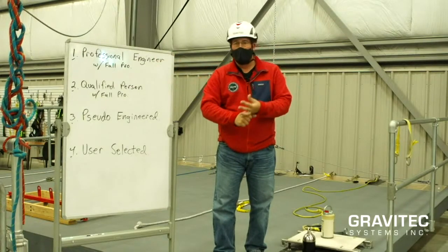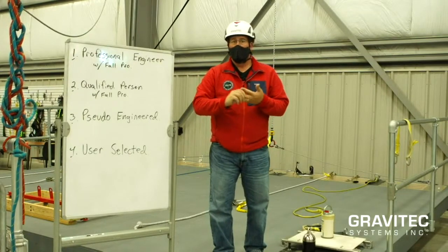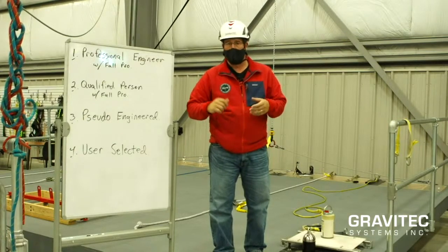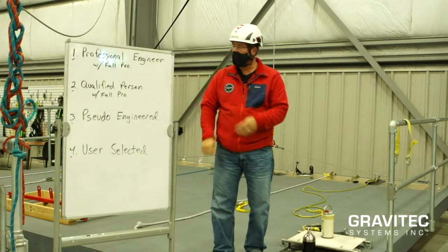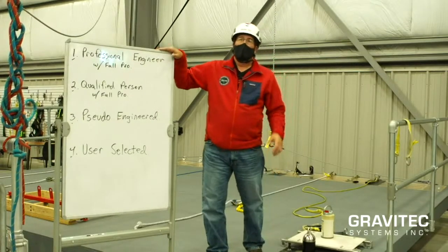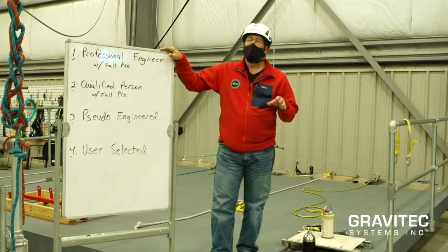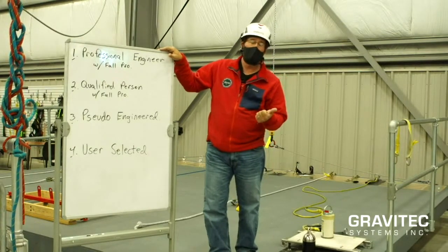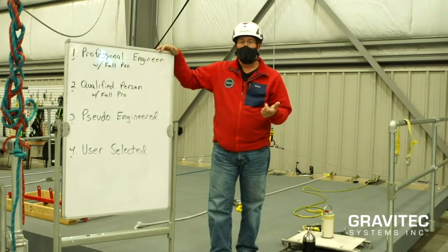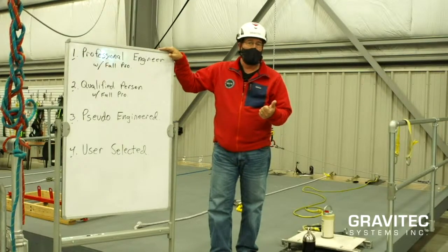Both of them are vetted for strength, both of them are vetted for compatibility, they're vetted for location, and ideally they're supported with documentation of drawings, user's guide, inspection requirements, and strength requirements, okay? So those are ideal. But like I said, we recognize not everybody can get permanent anchors everywhere, okay? A lot of times you don't own the buildings that you're working on. Neither of these anchors are very fast, okay? And neither of them are very cheap, okay?